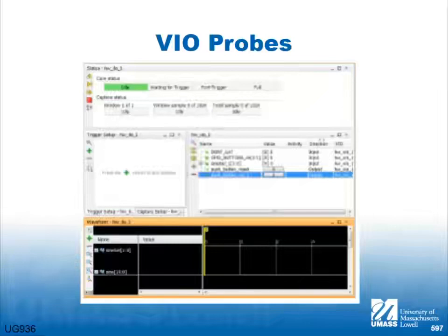What you do is you put it into an FPGA, right? We build it in ASIC, but we put it into an FPGA. We built that algorithm that walked the error through. We had the actual results and the expected results, and we compared them. So we were putting the response checker in this, and we figured out what the clock was. Of course, it was too slow, but it didn't fill the FPGA. So we put about 10 copies of the circuit in, and we indexed them so they were all looking at a different space in the algorithm.